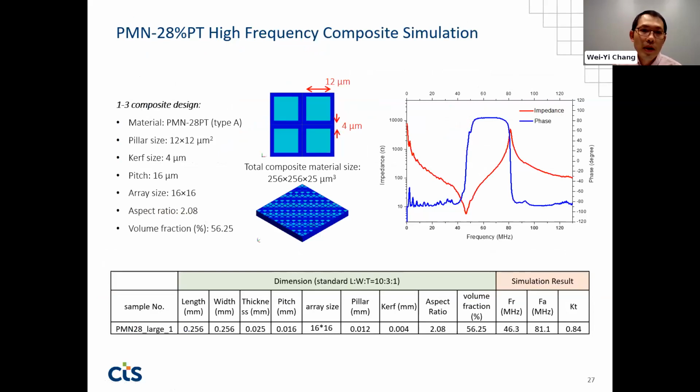And the last one will be the high-frequency composite simulation. Here, I took some parameters like kerf size about 4 micron and pitch size about 16 micron, and the piezo size will be 12 micron. We put these parameters into the simulation to see if we can get similar performance to what we make on the manufacturing side.